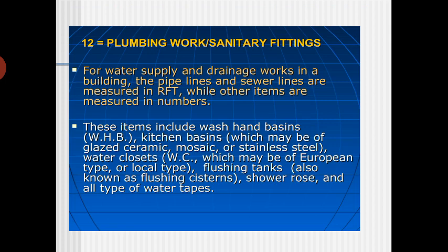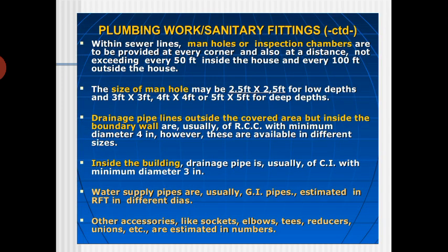Last one. Plumbing works and sanitary fittings. For water supply and drainage works in the buildings, the pipelines and sewer lines are measured in mm, while other things are in numbers. Square feet, that is measured in square feet, others in numbers only. These items include wash hand basins, kitchen basins, that is ceramic mosaic, water closets, and some of the shower cases and all other pipeline fittings. Plumbing works and sanitary fittings. Of course, you can go into detail one by one.